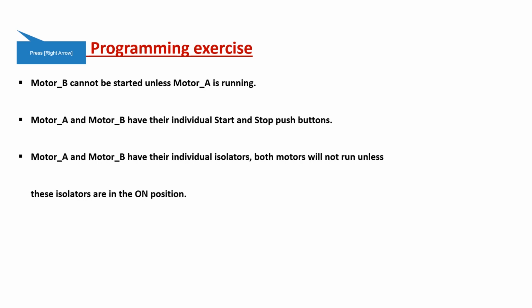This power supply is giving us 24 volts. That is what we're going to use on our control circuit, and we also want to use 24 volts to energize the CPU, which is the controller, the PLC.